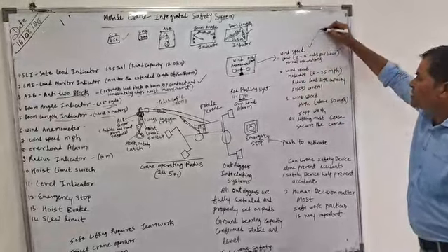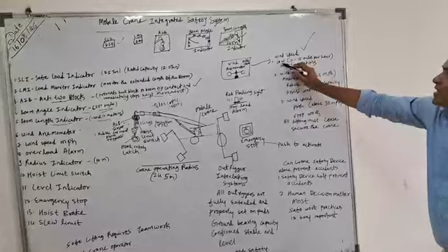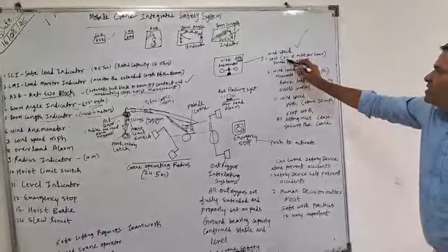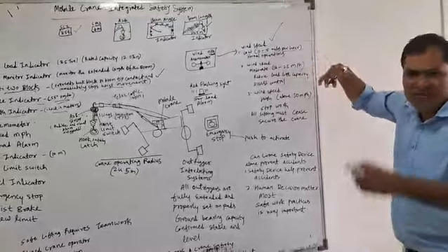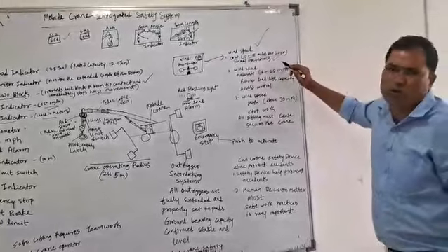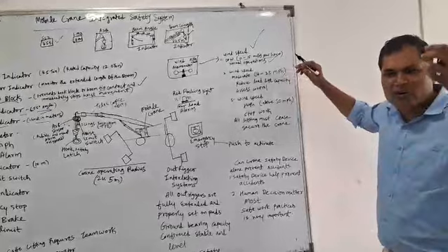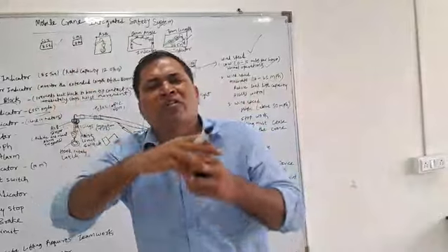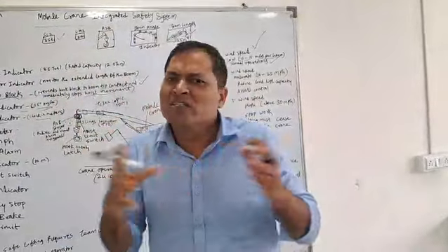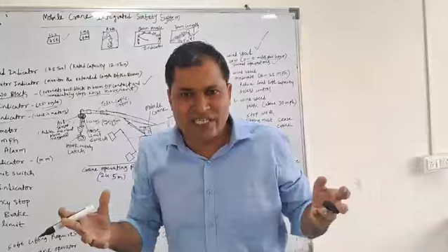For safe operation, it says low wind speed, which is 0 to 15 miles per hour. If the wind is like this, you can go for normal operation. Your activity going on for more than 1 hour, 2 hours, or a whole day, you can work, because the wind effect is in a normal condition.